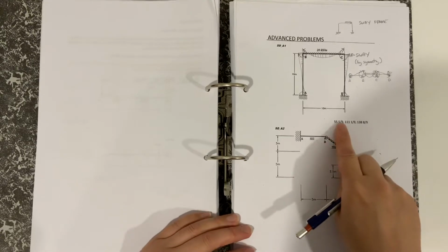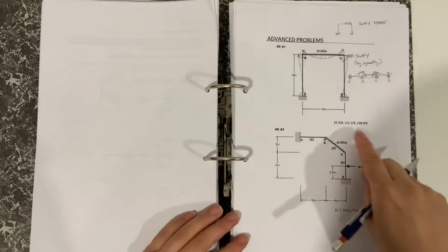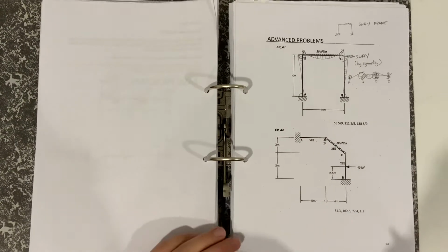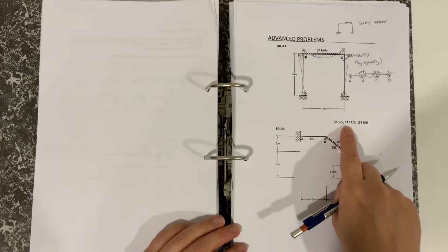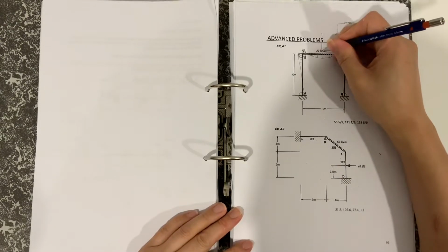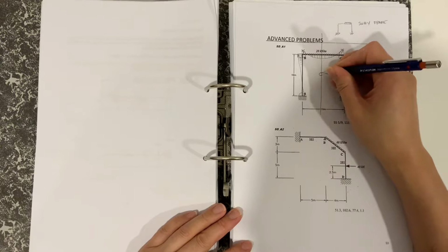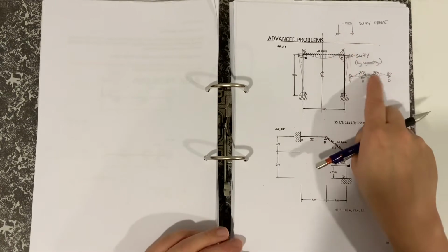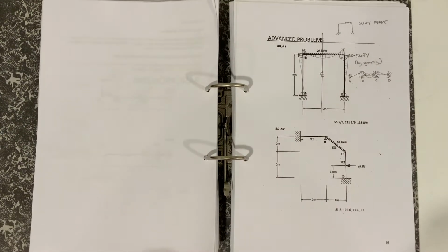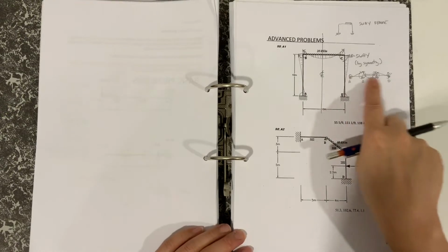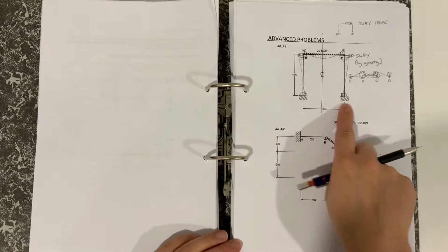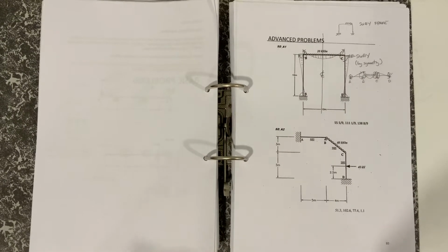So again, on the Dropbox, you would find a full worked solution for this one here, and then you would be working out these key values, 55, 1, 1, 9, 1, 3, 8, 3, 9. Okay, and remember that's a line of symmetry. So it is a sway frame, but you can say it doesn't sway because of symmetry of the load, and for that reason we can do what we've done here, and it's exactly the same whether you solve that problem or this problem using the slope deflection method.